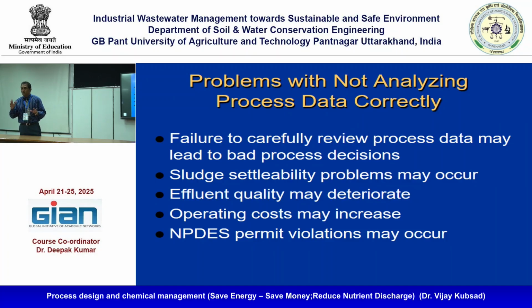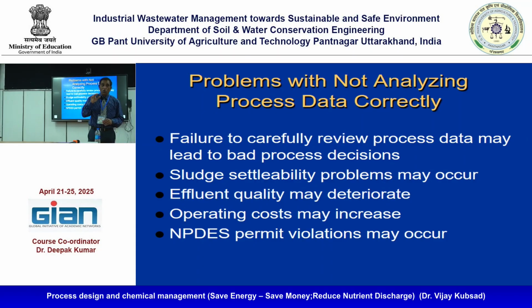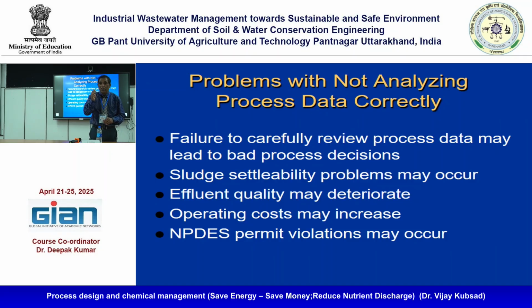If a lot of blowdown water is coming from air conditioning or different sources with a high TDS, and it is passing through, you should understand whether that is required to be analyzed. Why are you not putting limits? That is why you need to understand the source of the wastewater, which industry it is, and from the industry, what is entering, right?